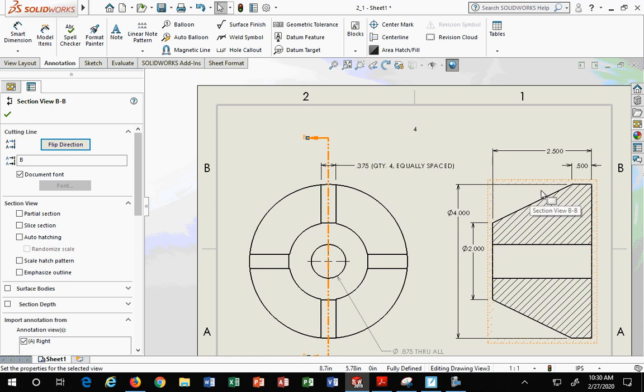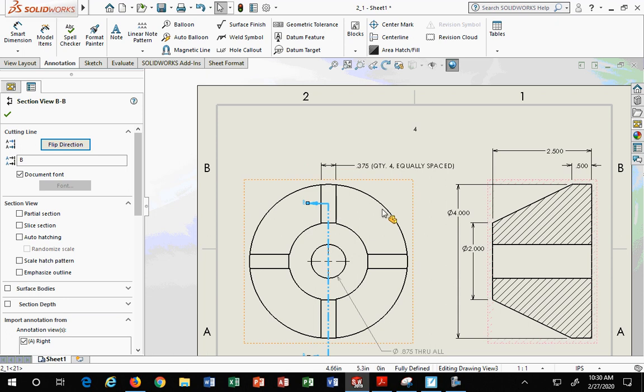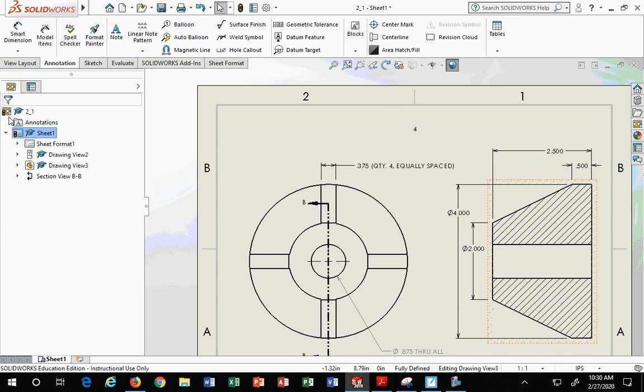you'll notice that it wants to update. If I drag this a little further down, whatever I do when I move it, and I hit OK, you'll see your other objects turn into little hatch looking things. You see that little orangey hatch thing? You have to update your drawing. Because when you affect this, it thinks that you're affecting what you're cutting. So if you accidentally drag this into the part, you hit OK and update your model, watch what happens.